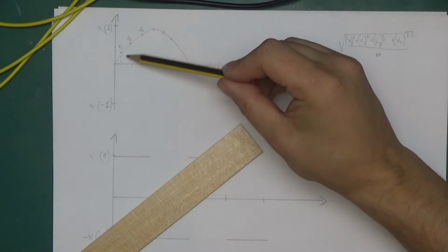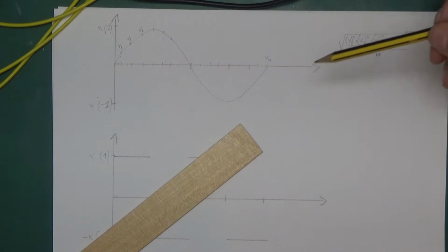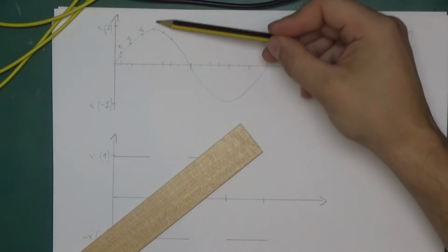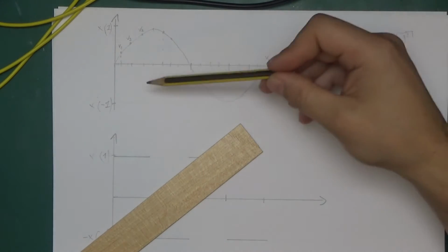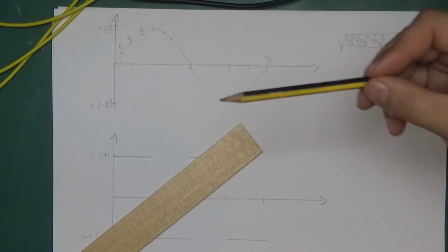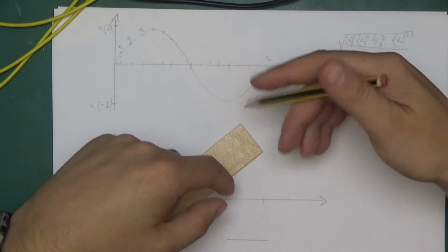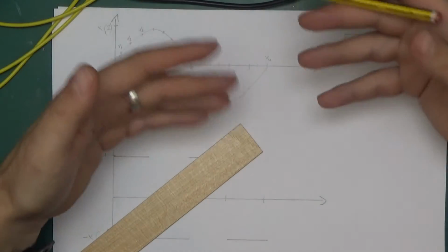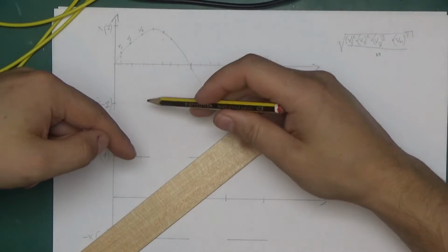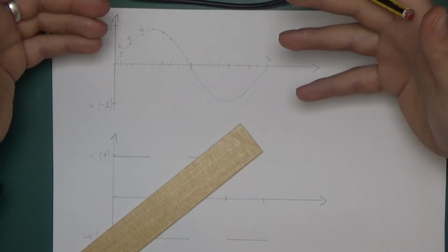The important thing to note is that there is no frequency element in this equation, and the RMS value is entirely independent of the frequency of the signal. As long as the shape of the waveform and the amplitude don't change, the frequency can change as much as it wants, and it doesn't matter. The RMS value of that signal will still be the same. However, it is important to remember that the circuitry inside a multimeter is limited in frequency, has its own bandwidth. So once it goes past that bandwidth, the multimeter is unable to make all the measurements that it needs. Things happen simply too quickly, and the multimeter is not keeping up.